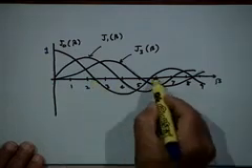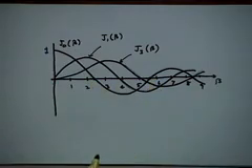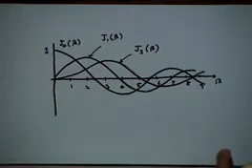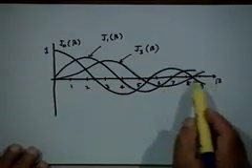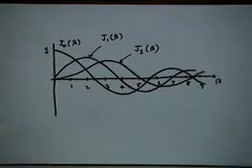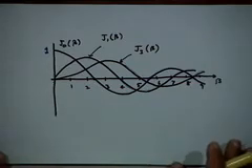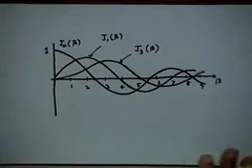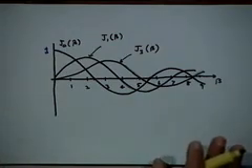So for these values, the carrier component disappears and you have all the energy present in the sidebands only, whereas for large values of beta, energy is equally distributed in the various sidebands, and a very large number of sidebands, because they all decrease. So I hope with this picture you have a better feel for the Bessel functions. What do they look like as a function of beta? And if you were to